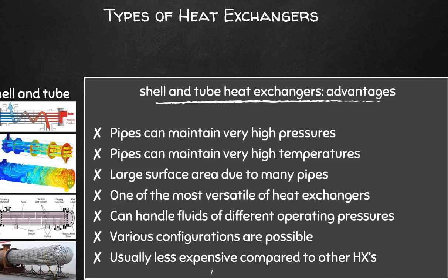Now, the shell and tube heat exchanger obviously uses tubes. It is by far the most commonly used type of heat exchange equipment that you'll find. So if you are ever in industry, you can go to any part of the process and you are typically going to run into a shell and tube heat exchanger.